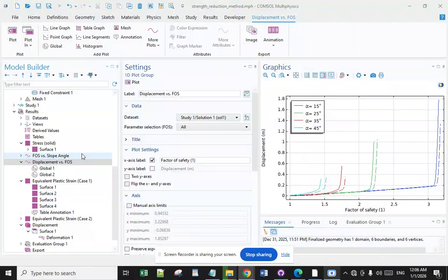The design factor is defined for an application, generally provided in advance and often set by regulatory building codes or policy, and is not an actual calculation. The safety factor is a ratio of maximum strength to intended load for the actual item that was designed.